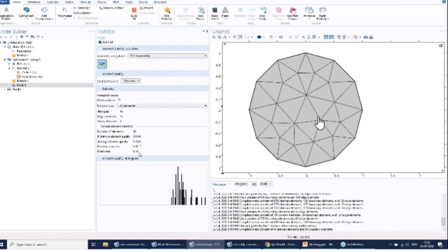Okay, which means that there is a lot of approximation this mesh has done to the solution. Next, in this mesh statistics you get a lot of information, like there are various quality measures here, like skewness, maximum angle, volume versus circumradius, and so on. Right now the quality measure is based on the skewness, and here you can see that the minimum element quality is 0.6744, average element quality is 0.7826, element area ratio is 0.4, and mesh area is 3 meters square.